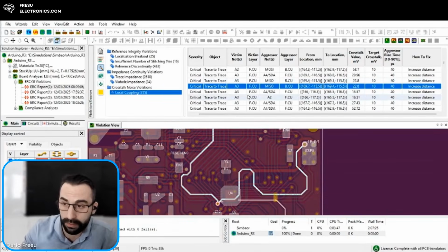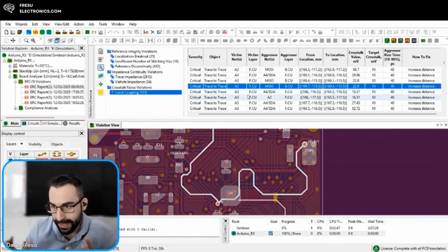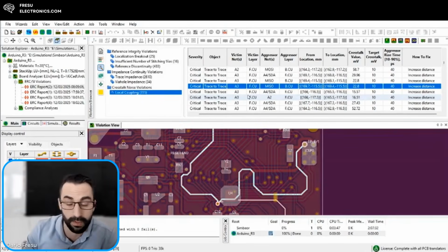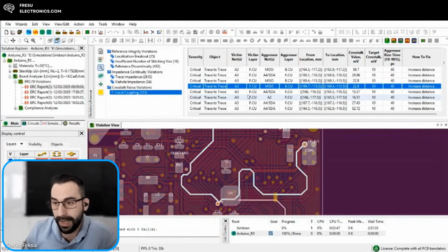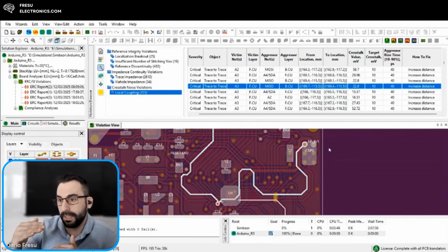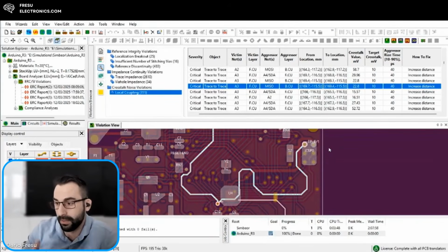But if you want to, then you can check also, how is the signal? What are the reflections? How much reflection do I have? So you can simulate all of that. You can see the eye diagram. So it goes much more in depth. And also, if you localize the analysis, then you can see how the fields will spread. So if you choose a certain stackup, you can simulate how the fields in between. So how the magnetic field, the electric field, displacement current, and the power flow. So it gets much more powerful than that.